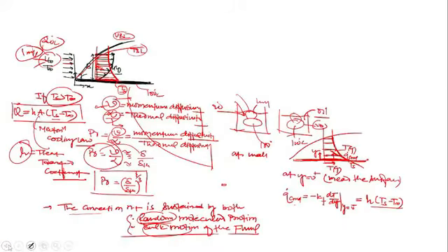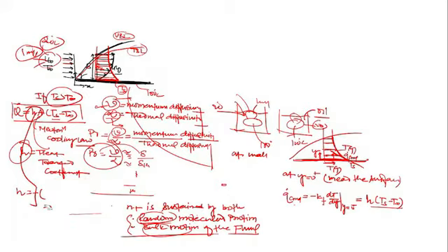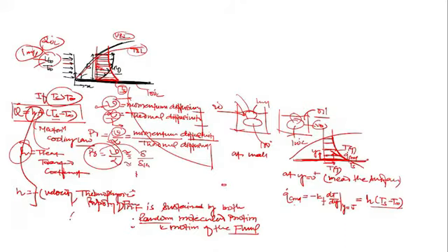So at the last, my dear students, what do you know? Okay, this h is very complex because it depends upon a number of parameters. Yes, very good, Deepika. h is a function of what? First, velocity, then thermophysical properties of the fluid, and also the characteristic length of the object.